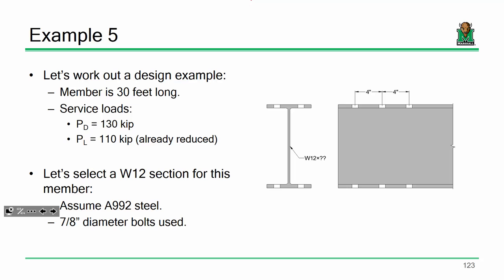There are a lot of design aids that we're going to use throughout the semester, and if they're referring to W shapes, those design aids are going to use an Fy of 50 and an Fu of 65, because that's the preferred material spec anyways. Make sense? Okay.